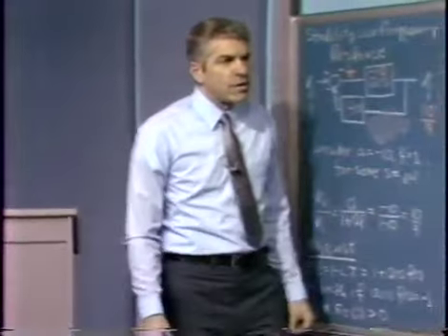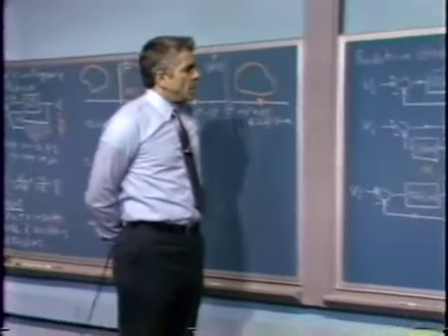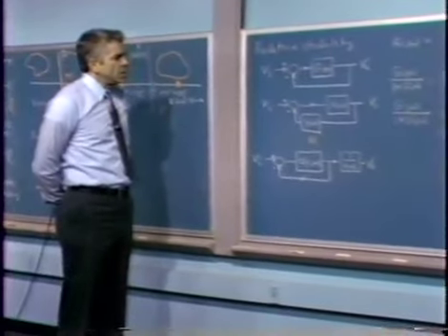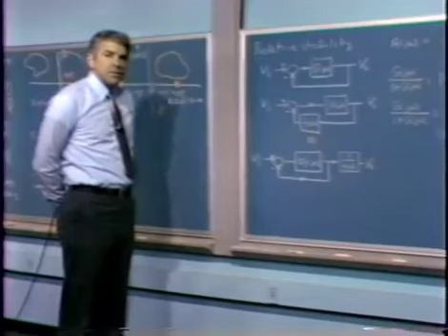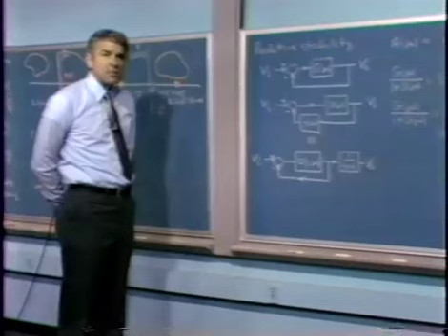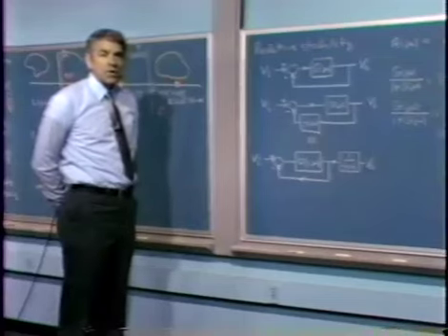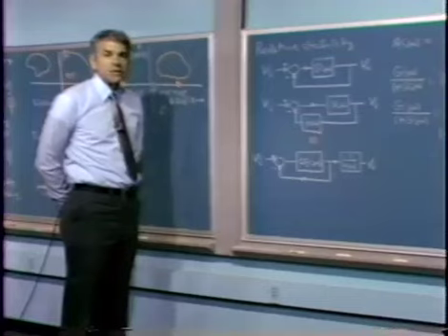What we do in this sort of a development, in other words, when we evaluate stability based on frequency response, is to really look at features of the closed loop frequency response of the system, and in particular look at things, for example, like the amount of peaking that we get. We excite the system, look at its sinusoidal steady state response, and we see, for example, the amount of resonant peak we get. We feel that a larger resonant peak indicates a relatively less stable system.